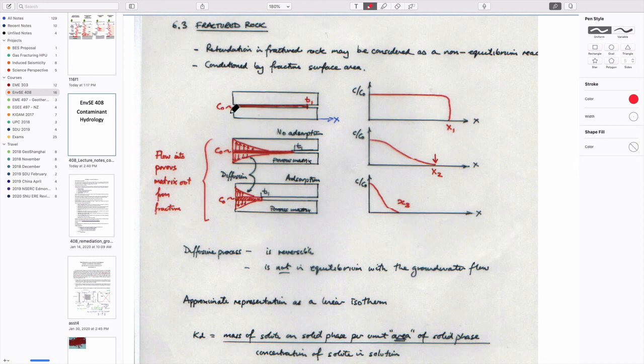And so the other reasons here would be, if you imagine a plume going down a fracture to get to some place, you'd have a very sharp front. No sorption occurs onto the material that's around it, and so everything that starts up at the upstream location ends up at downstream. And so you'd expect this kind of plug flow. If you allow the material to be porous, so that there is water in the pore space, then as it goes downstream, stuff can diffuse into the water by molecular diffusion, and as a result some of the mass will be lost.